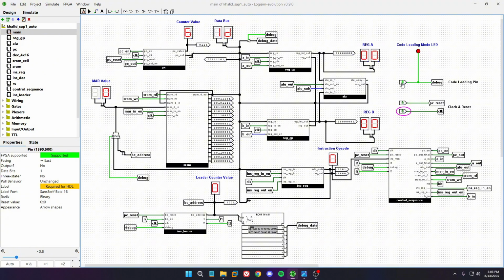We can now just turn off the debug mode, and the CPU is now in the CPU mode state, which is the fetch, decode and execute state. So first we need to do the PC reset so that we can reset our counter, and now we can fetch, decode and execute it with the help of the clock pulses. It's exactly like before. We have a total of 5 instructions. Each instruction takes 6 T steps, so in total we need to give 6 times 5, total 30 clock pulses to execute all the instructions.